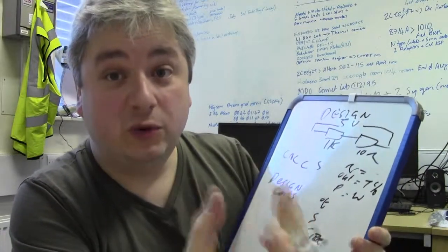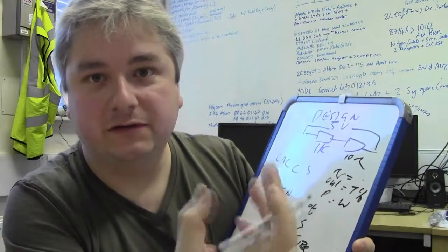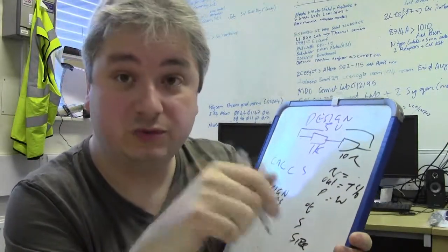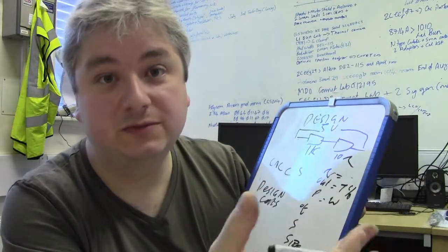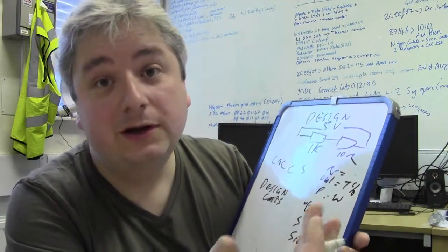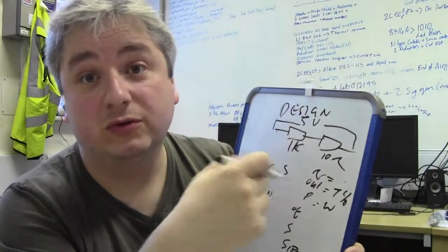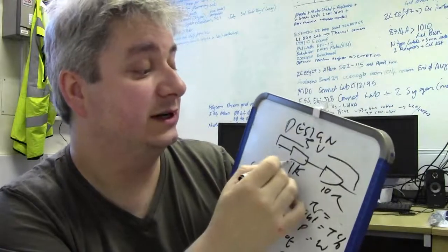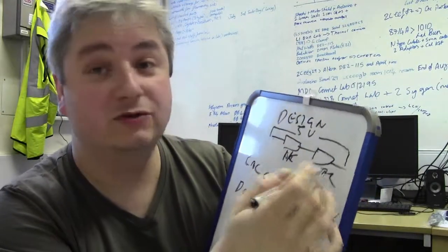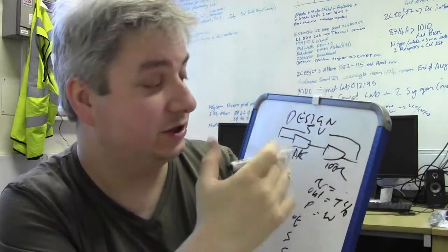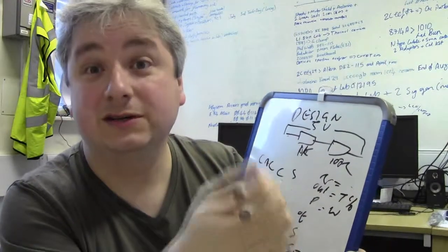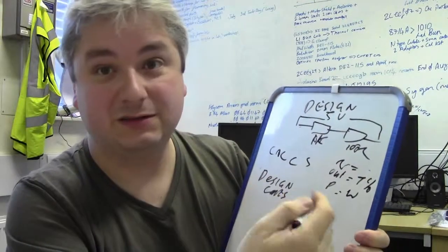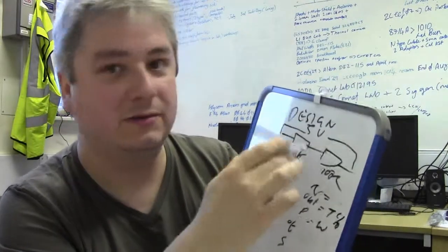Size: does your circuit have to fit into a very small place? Is it quite confined? You have to aim for small components. Small sizes means low wattage generally. So you may have to go back to your drawing board and redesign your values so that you have a lower wattage dropped across your resistors. So instead of a 10k, you might have to change this to a 10 and 100. Keep your ratio, you keep your voltages, and what have you. Current goes down, so therefore the power dissipation is a lot lower. So you can fiddle about with size by going back to the original.